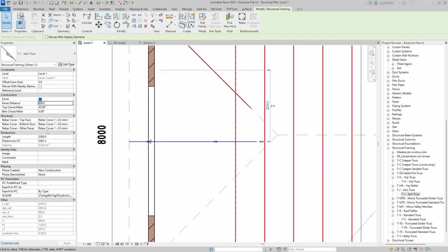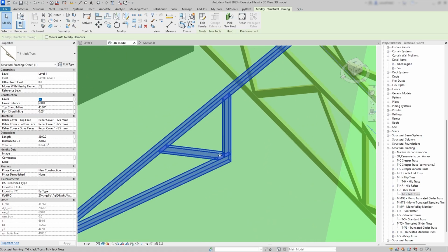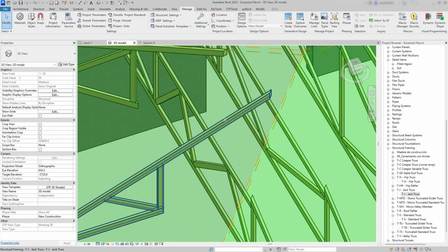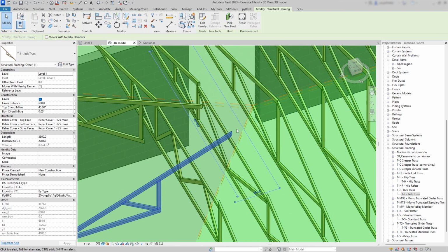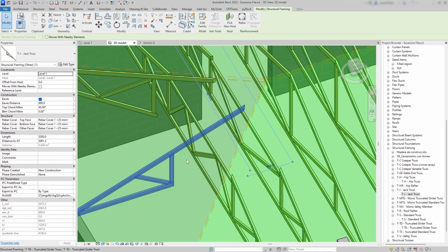In addition, we have one miter cut parameter for the top chord and another miter cut parameter for the bottom chord, and these can be modified independently. This is important because in some cases, the truss connects perpendicularly to another truss, while the top chord extends to a different element where it may connect at 45 degrees or not. In other situations, the opposite can happen. For this reason, the top chord and bottom chord's cut parameters are handled separately.